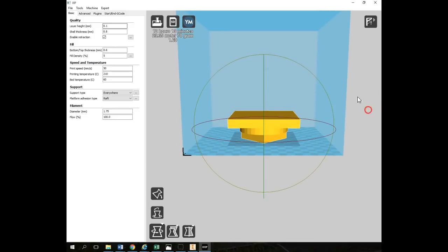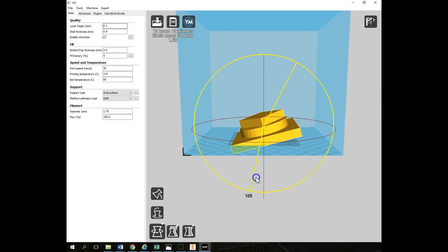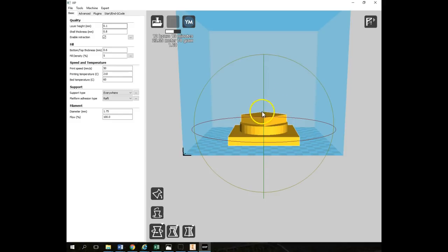If you put it the other way, with this large square on the bottom, it's going to be a much better print because these will be smoother surfaces and it'll be able to give the detail it needs there. But that's just part of the fun of learning 3D printing, as you learn what the best method is for your particular cases.